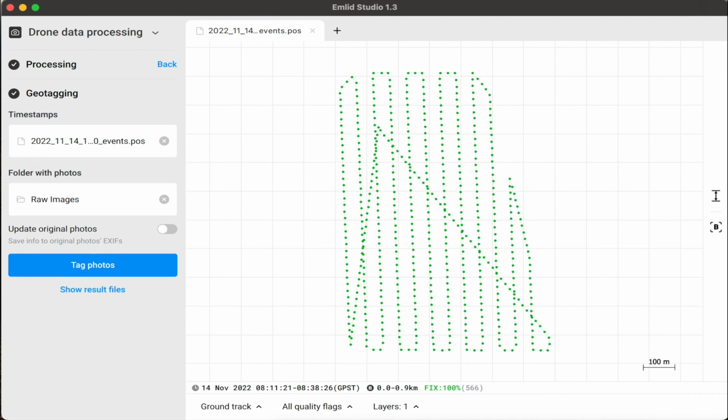Second method of verification can be, if you have a base map of that area, then overlay the geotagged images on top of a base map. Base map could be satellite imagery or topographic map that covers the same area. This helps in visually comparing the location of the geotagged images against the known landmarks or features. Also, you can check for the alignment. Carefully inspect the alignment of the geotagged images with the underlying map. Look for any discrepancies or misalignments that could indicate inaccuracies in the geotagging process. If not, then you are there and you got the perfect solution.